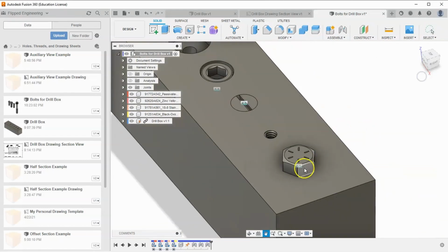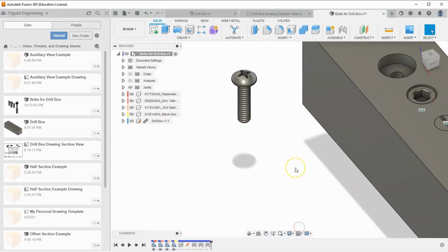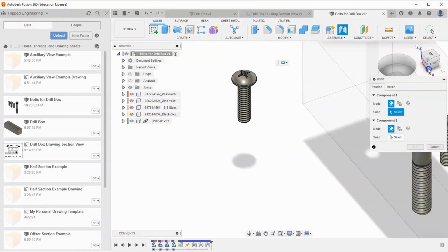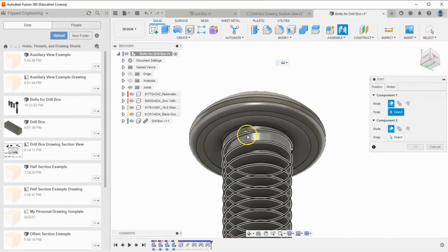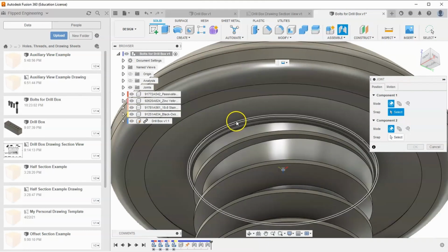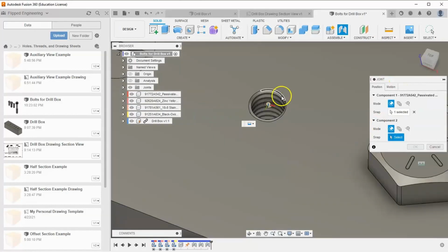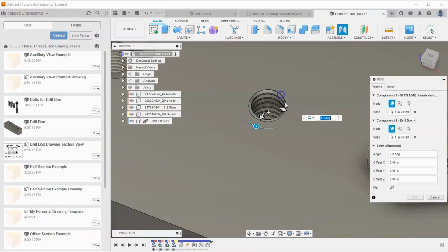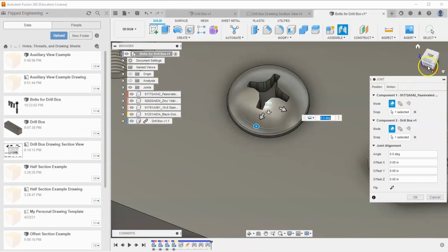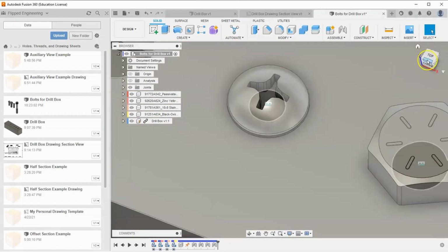And then we can just real quick do the last one. Same thing. We'll go to joint. I'm going to go ahead and hit J on my keyboard. And same thing, get that bottom circle there to go on this circular face. And once again, you want to make sure you get the center selected. So dance around it until you find one that locks it onto the center, and click. And you'll bring it in and hit OK.